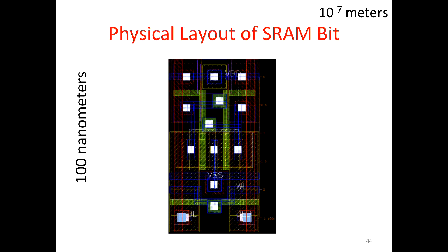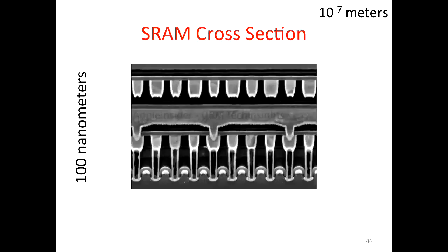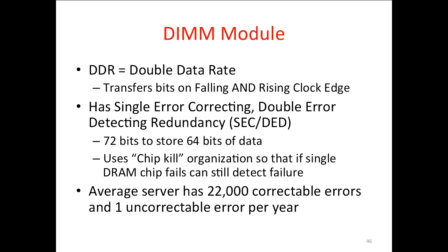Like all those caches, those huge memories. The L1 caches, the outer caches, the register files, they're all SRAM-like structures. And making those dense is really important to the cost. So people spend their lives optimizing how these things get packed together. This is just looking at how it's laid out in cross-section, bits in an SRAM. I think it was actually off an Apple chip. Somebody looked at what they were using in their SRAM technology.